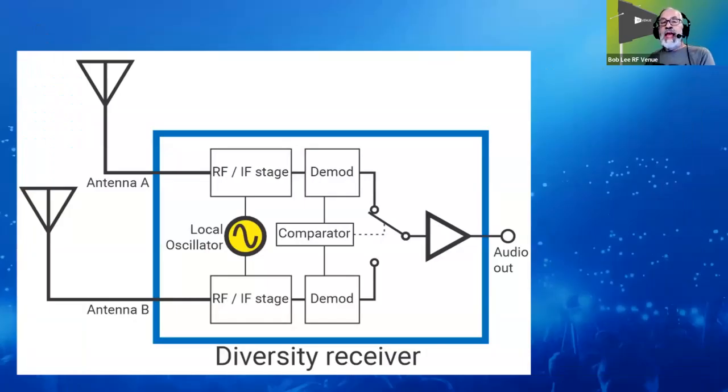So the receiving end is where the radio signal will get picked up and converted back to audio. Professional grade analog systems use diversity reception, which employs two antennas and receivers that select audio from the two antennas and RF stages, I should say. And the receiver selects audio from the antenna input that has a stronger, higher quality RF signal.